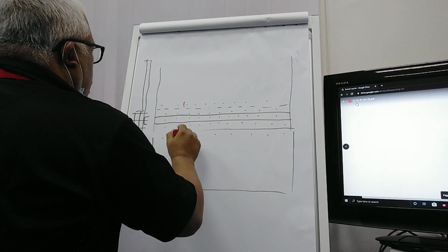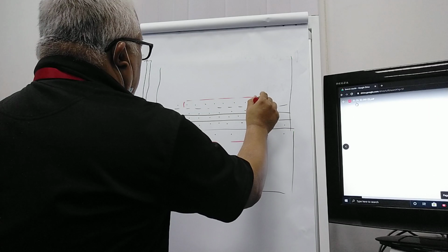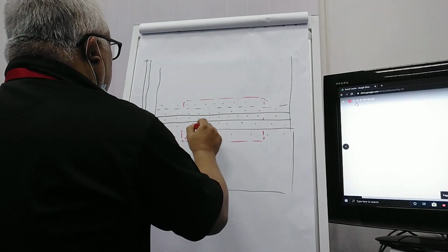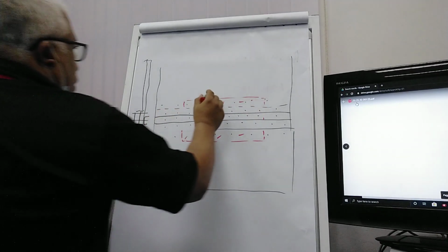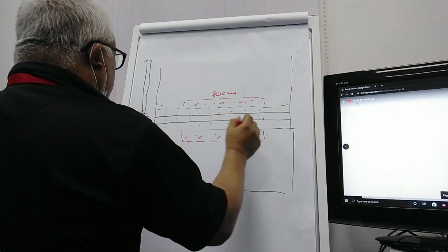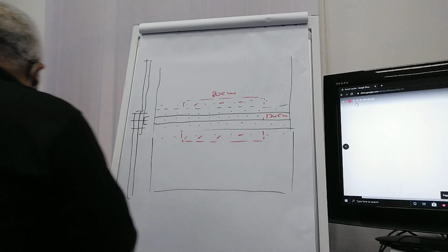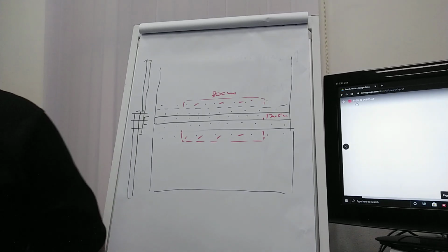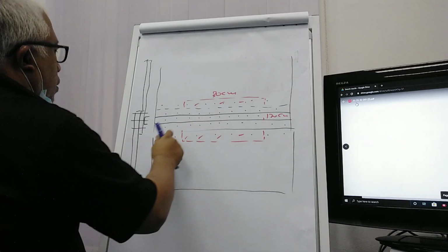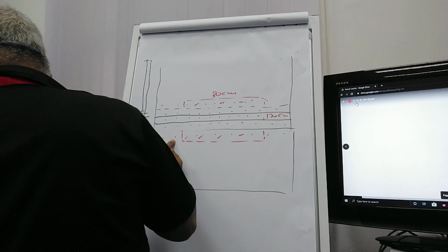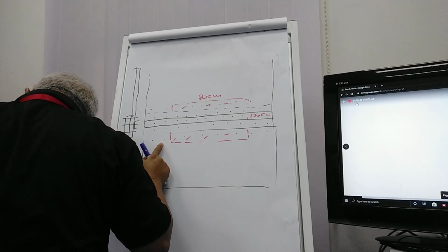Okay. So this one is cut off. And the dimension here is 30 cm, and here is 120 cm. Okay. So what do we do? We put a doubler repair. Okay. We cut off this area, and then we install a doubler outside. Okay, outside.